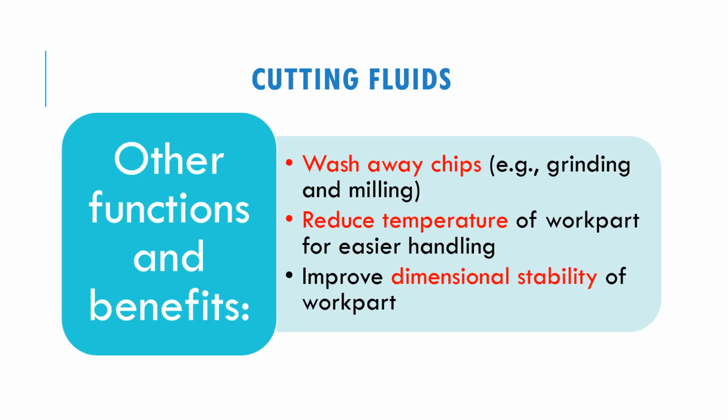Other functions and benefits of cutting fluid are, for example, it can help in washing away the chips in grinding, milling, drilling, and also the turning process. So it can reduce the temperature of the work part for easier handling, because the chip is very hot.